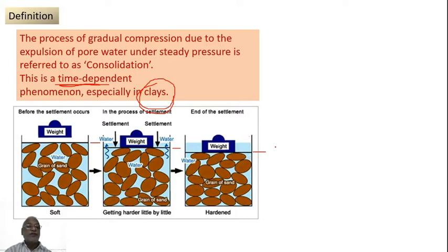There it stops. So we say that it is completely consolidated, right? As long as pore water pressure is present, it is trying to go out, the consolidation process is happening, and when the water under pressure goes out, and then the pressure of the water inside the voids is reduced to zero, we say that it is end of consolidation.